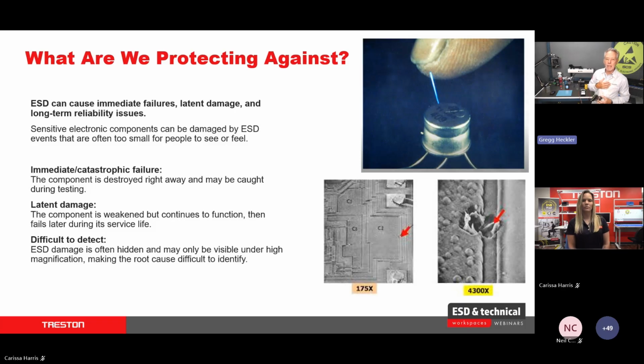So your body is conductive. You're wet on the inside and dry on the outside. When you sweat, that sweat layer makes you conductive. It's salts, minerals, things like that in your perspiration. And so when you walk across that carpet, you're going to charge up positive about 99% of the time. When you go over and touch that doorknob and you get a shock, that's because that metal doorknob is negative. So that's another way that we create an ESD event.